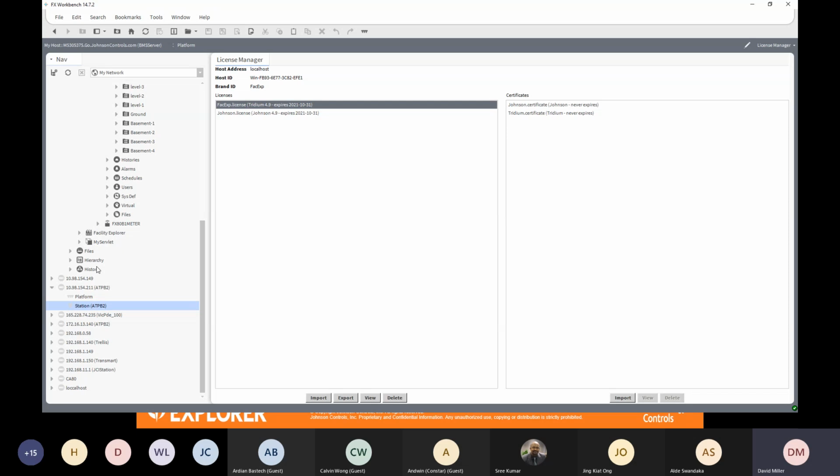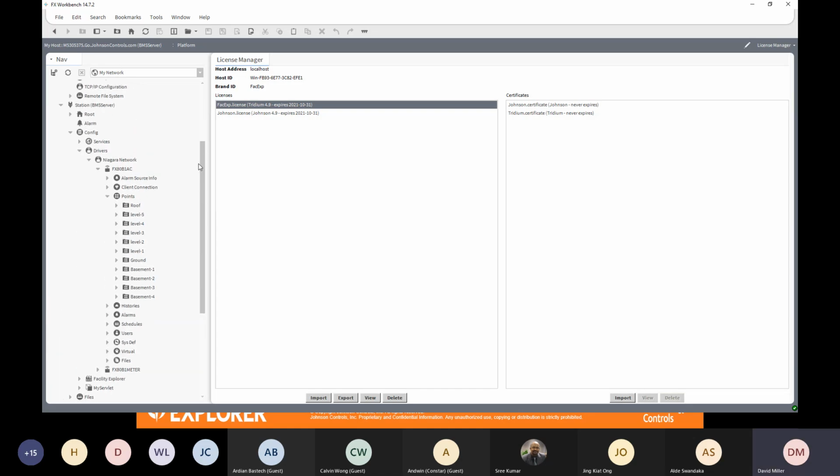So it's very hard to say, yes, 100% you can connect to a Distech JACE and do everything in the Distech JACE. What we can say is you can create a Niagara network and you can discover the Distech JACE, discover its points, map its points, put its points on our graphics.